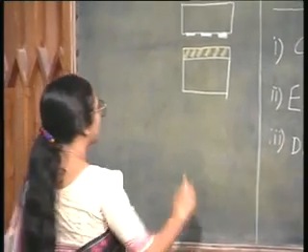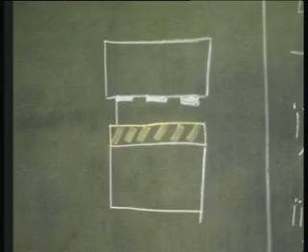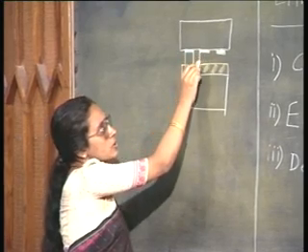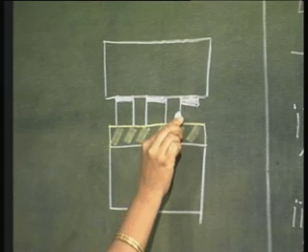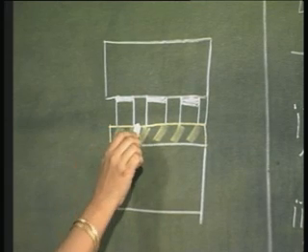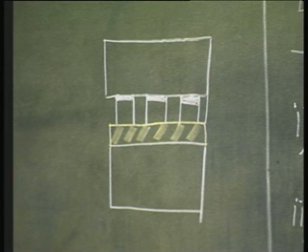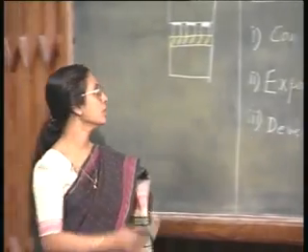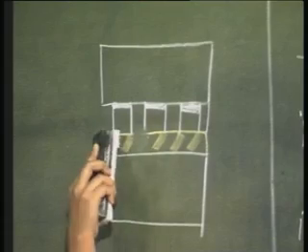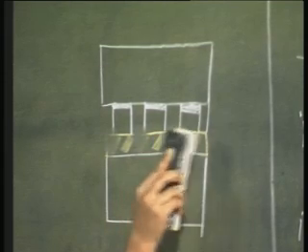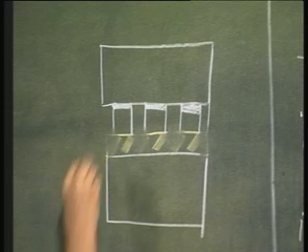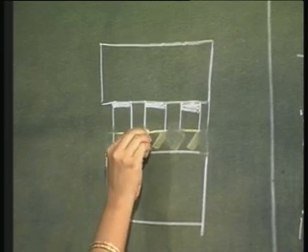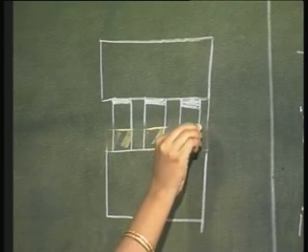Then what is going to happen? This is the portion which is exposed to the radiation, and this is the portion which is exposed to radiation. The photoresist directly underneath these is exposed to radiation, and now it has become soft, it is easy to remove. So, when I put it in the developer solution, these portions go away, leaving me with resist films only in the unexposed regions.